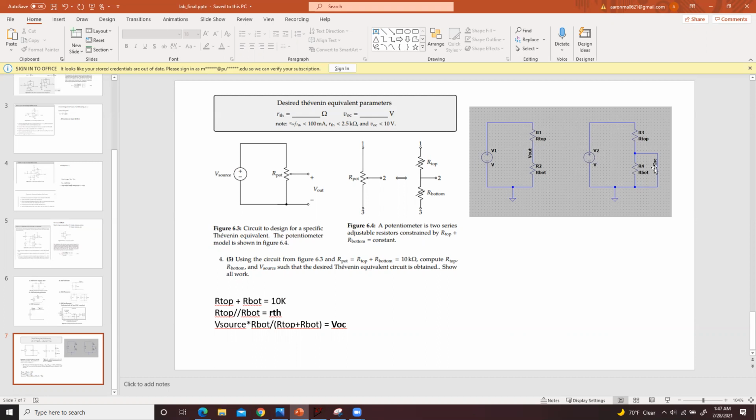When you test the short circuit current, you want to short this output to ground. Then the current that goes through this part is the short circuit current. That's how you do the measurement on the breadboard. I think this is the common mistake in the lab practical, so I just give you a quick answer in case you wonder. And if you have any other question for your lab practical, you can just email me.